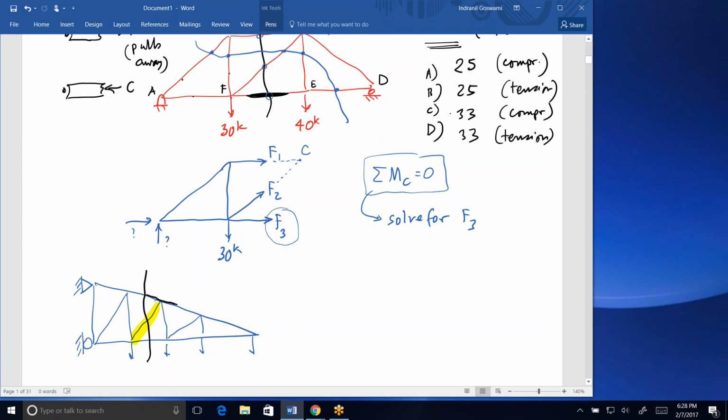But if I deal with this side, the right side of that free body, of that cut, I don't even need my reactions. So that whole idea that when you're solving a structural problem, the first step is calculating reactions may not be true, particularly for cantilever structures.